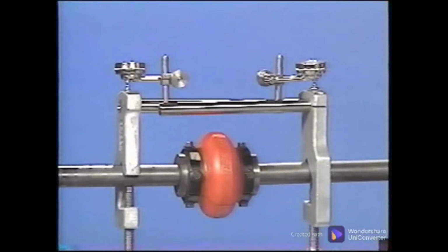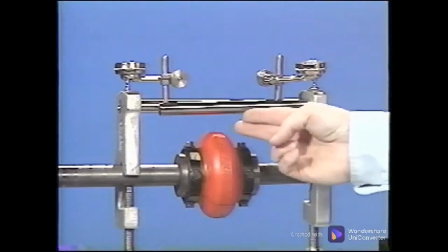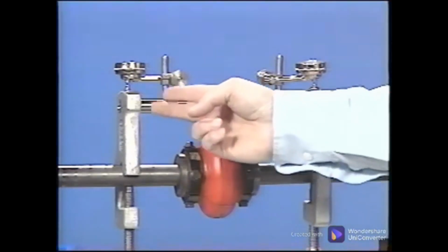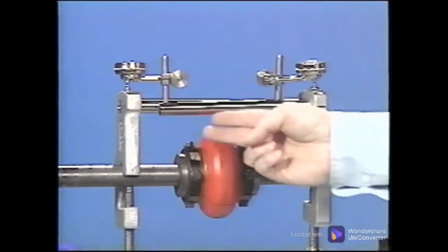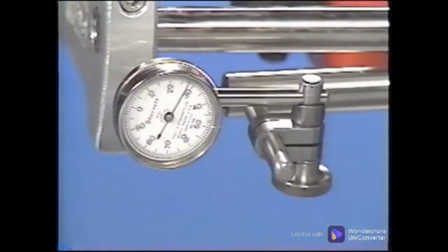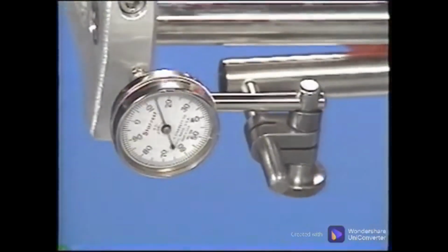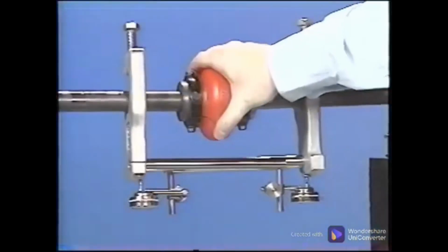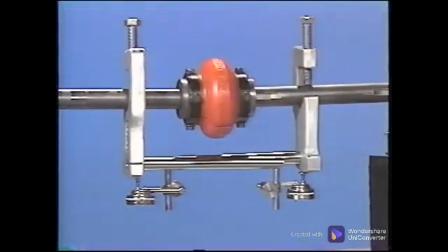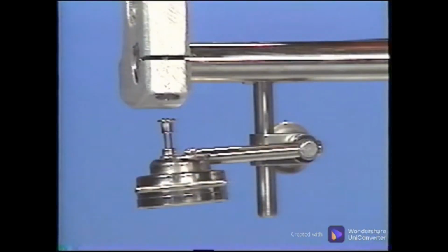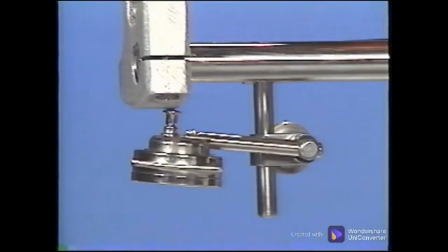For the reverse dial method, mount one indicator bracket on the shaft or coupling hub with its dial indicator resting on the opposite shaft or coupling hub. Be sure to mount it so the plunger is pushed in about halfway. The plunger must have some amount of pressure on it during a full 360-degree swing of the shaft. In severe misalignment, the plunger may either ride away from the shaft or bottom out. Either case will generate invalid data.